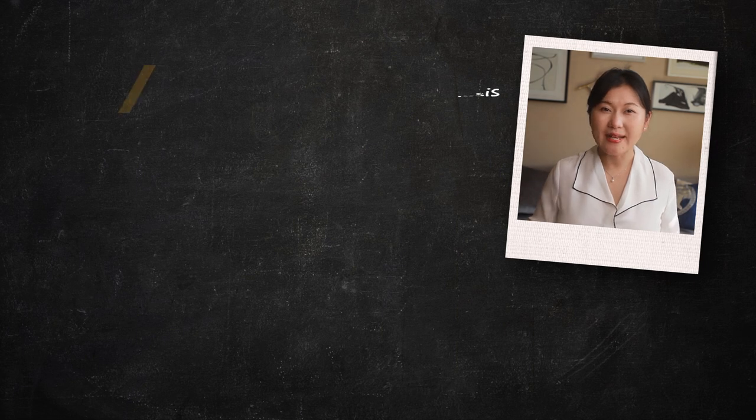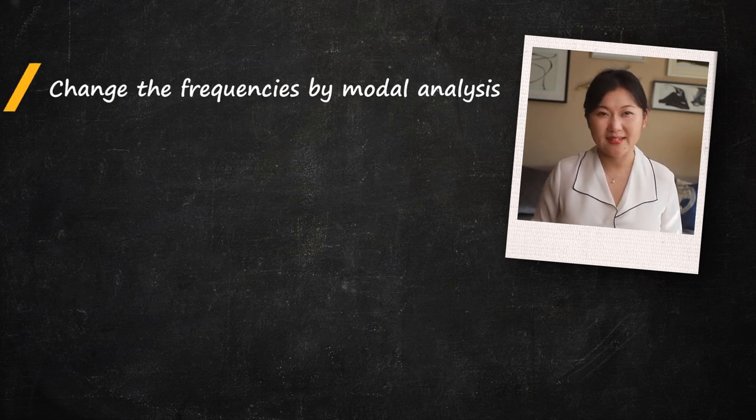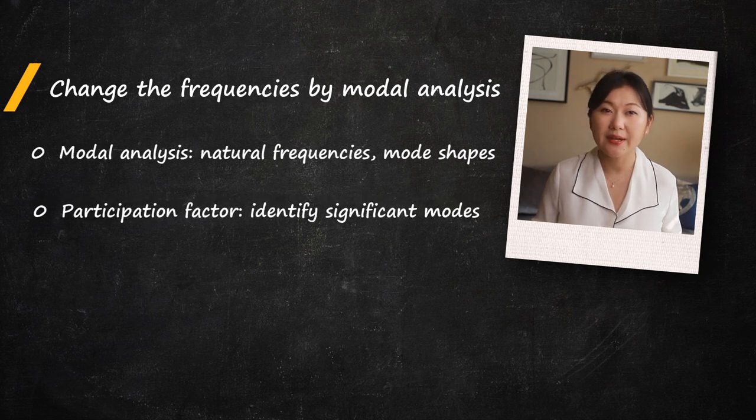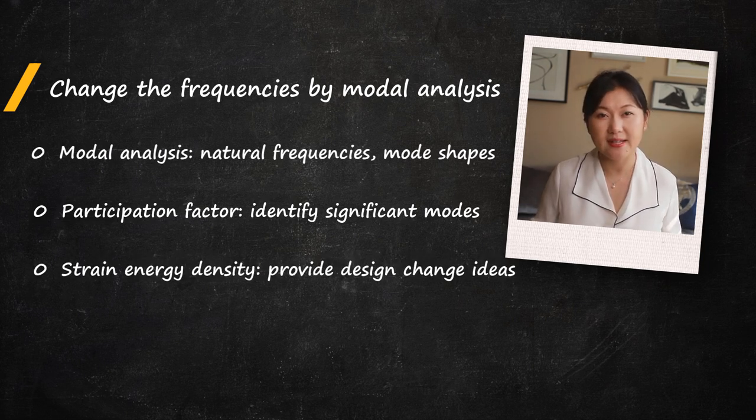In summary, we now know the importance of the modal analysis. It is a very useful approach to determine the vibration characteristics, the natural frequencies, and mode shapes of the structure. Once we extract the modes of the structure under free vibration, the participation factors can be instrumental to help us identify the significant modes that we need to focus on. And finally, the strain energy density output helps to provide insight regarding the structural behavior in design.